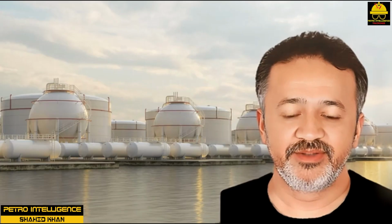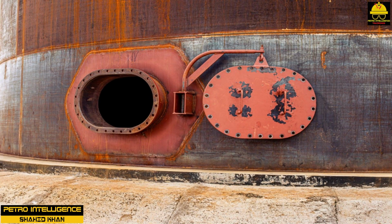Manways and manholes. The chemical processing industry uses manways as access hatches or ports into and out of tanks and vessels. These are used for visual inspection and access for cleaning. Manways are typically hinged for easy access. Gaskets are used to provide a positive seal, and a series of bolts and nuts are used to secure the door to the vessel. Opening, blinding and confined space entry permits are required for entry into a vessel.